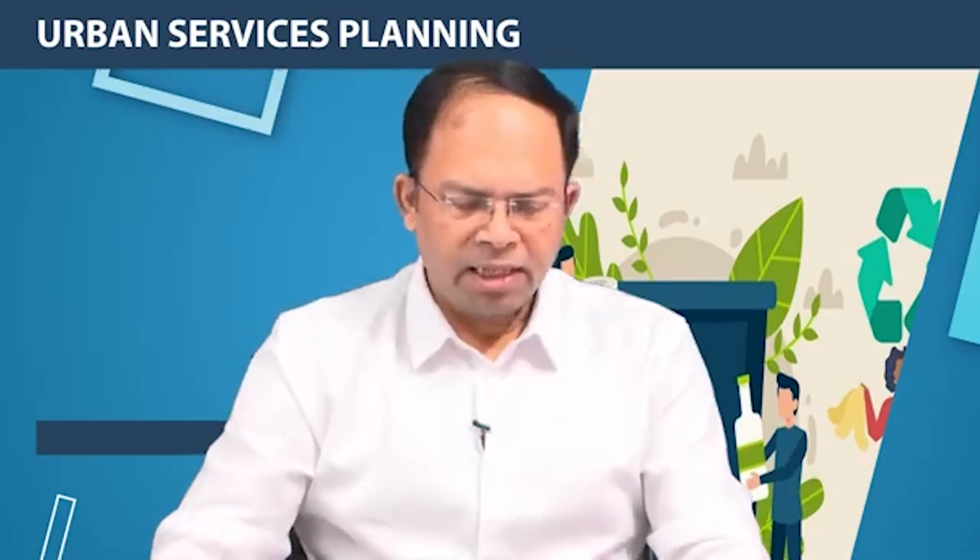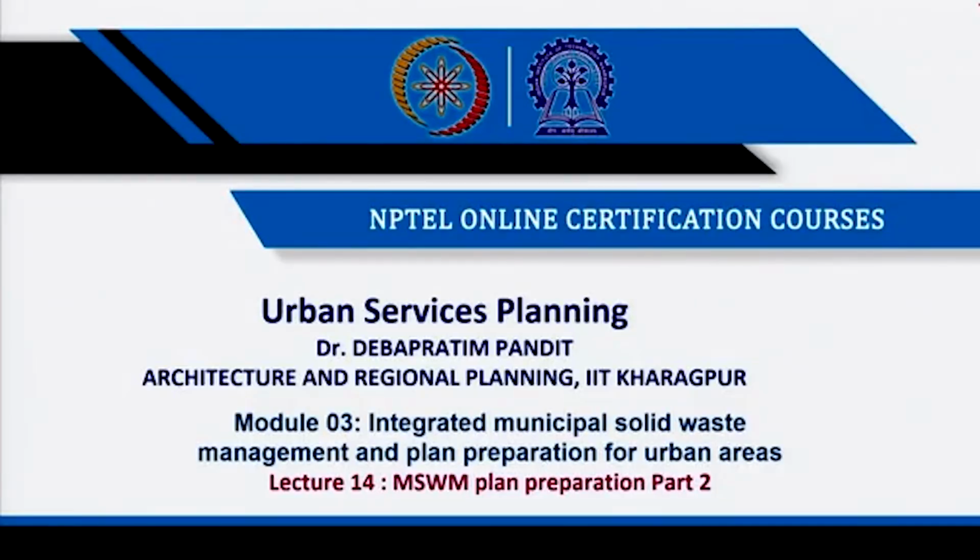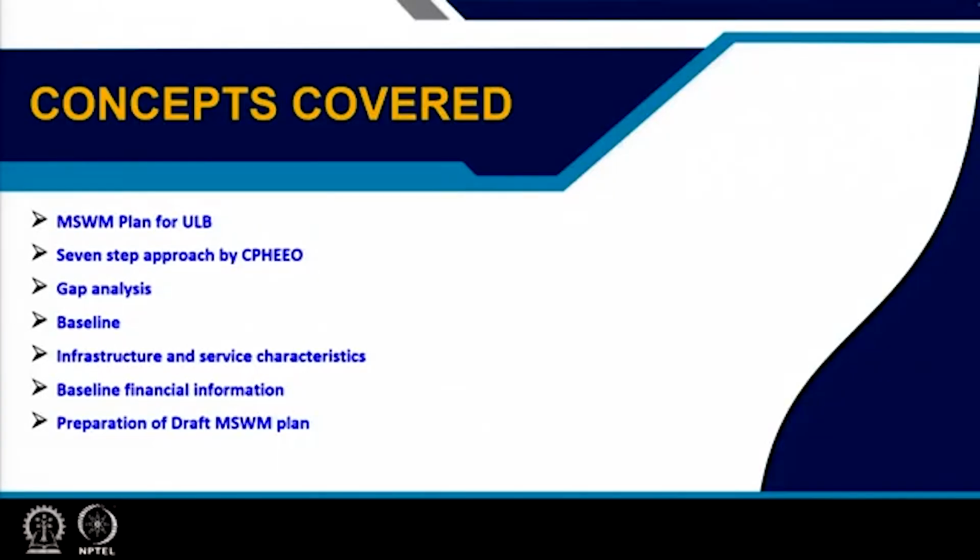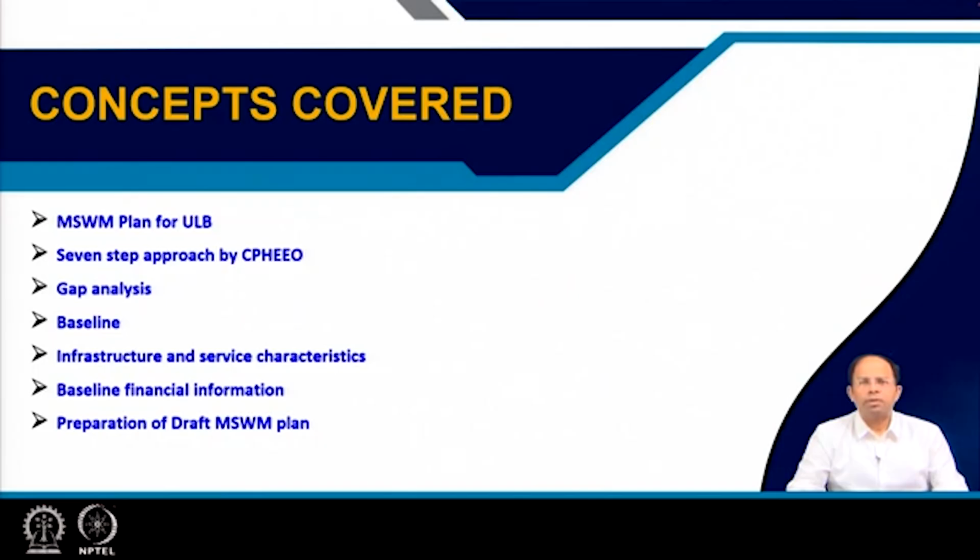Welcome back. In lecture 14, we will talk about municipal solid waste plan preparation. This is the second part of the lecture. The different concepts that we will cover around municipal solid waste management plan preparation for urban local bodies. We will talk about the 7-step approach recommended by CPHEEO. We will conduct gap analysis, baseline estimation, infrastructure and service characteristics determination, baseline financial information, and finally preparation of draft municipal solid waste management plan.